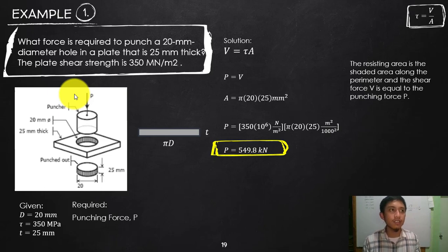If we are referring to how much normal stress it will carry, that is the normal strength. If we are talking about how much shear stress that material can carry, we call that the shear strength or tangential strength. So that you will differentiate when we call this strength and when we call this stress.